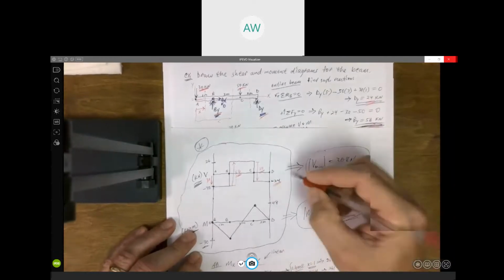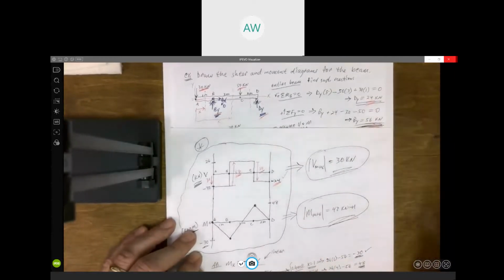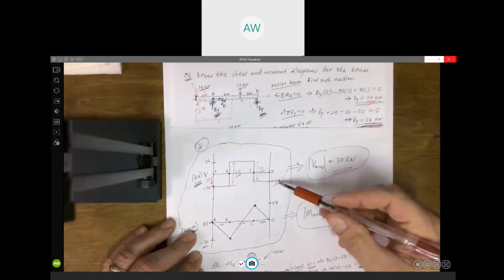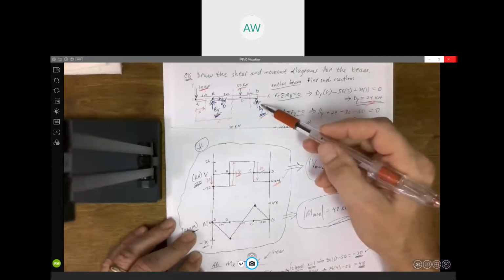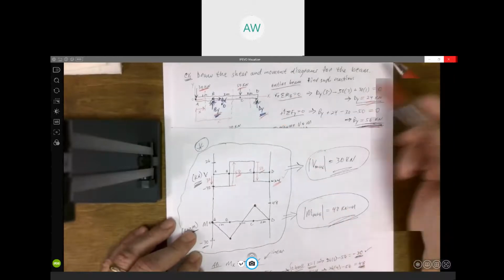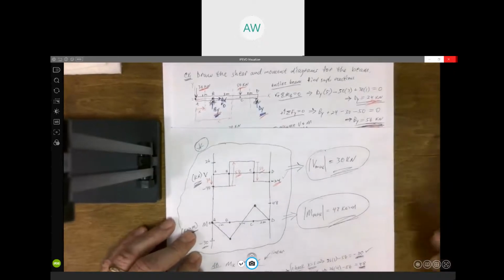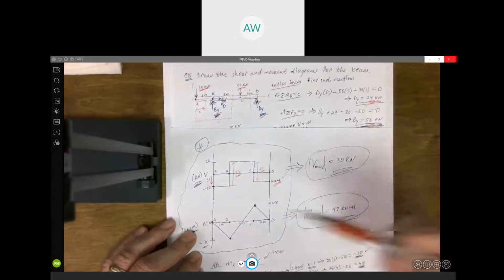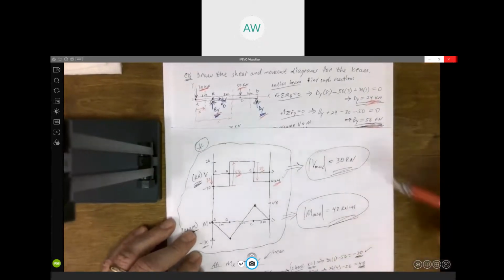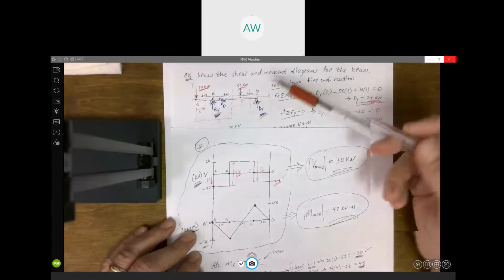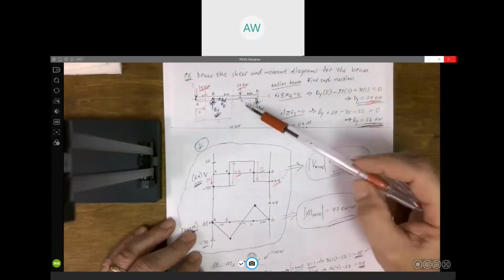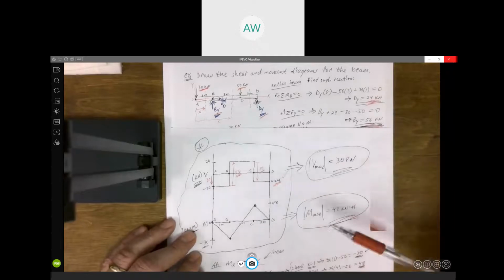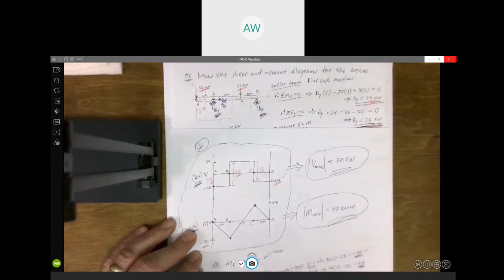And this is a way we can check ourselves. If we don't wind up at the same value as our support reaction force there, then we know we did something wrong. So now that we know this, basically all you have to do is calculate the support reactions, and you should be able to draw the shear diagram without doing any other calculations, really, other than subtracting numbers.